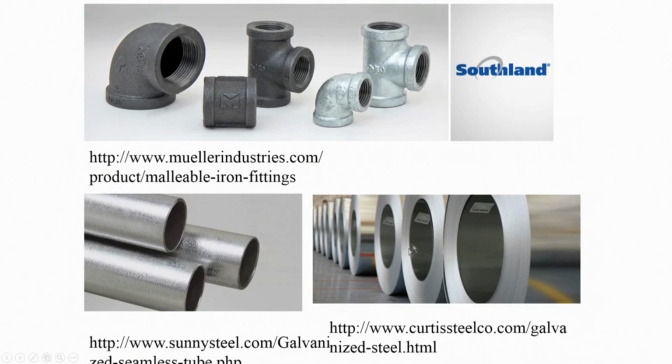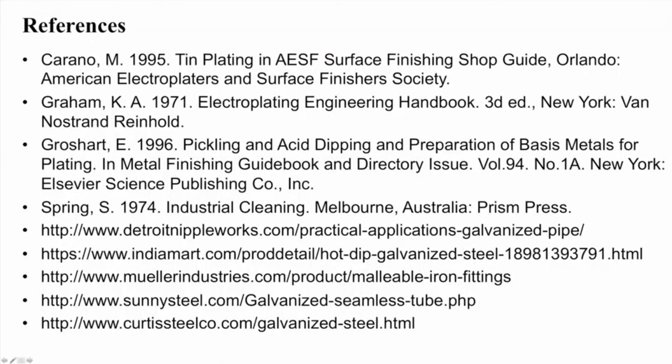So, zinc coating offers corrosion resistance, particularly when you are looking for general corrosion resistance in a normal environment where there is not much humidity or the temperature is not so high. And on top of that you can also have a very thin painting layer, so that it offers further resistance to oxidation. Thank you very much.